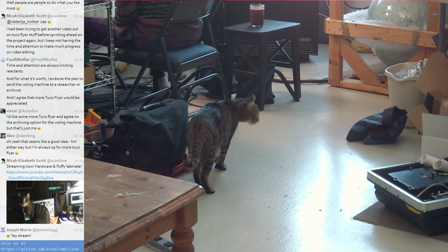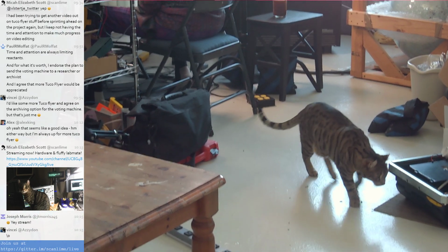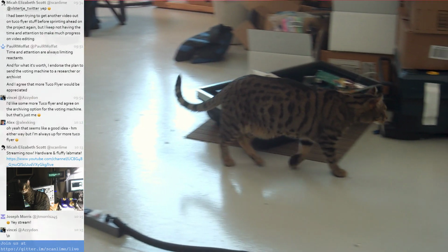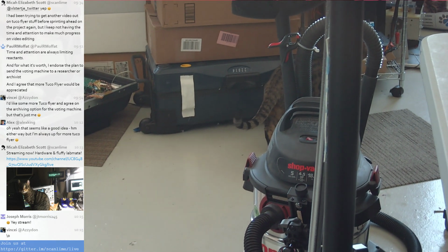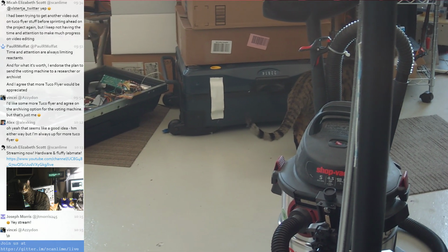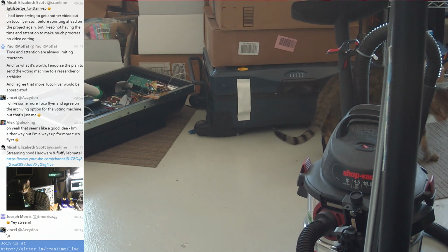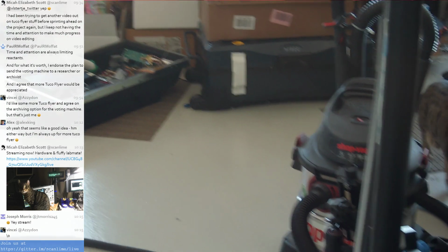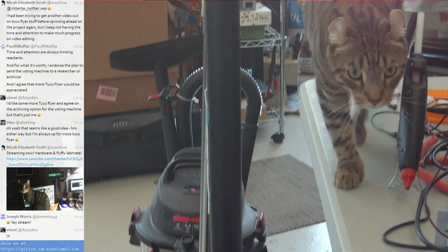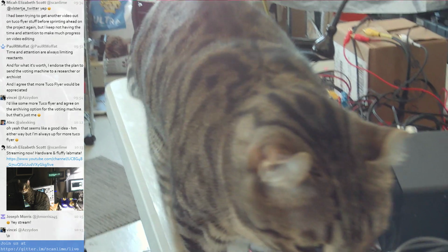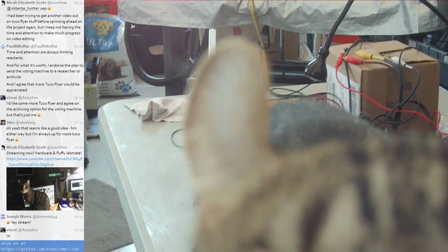There's also another pretty severe problem I've been repeatedly running into, where there's an oscillation involving this recovery feature that's designed to keep the gimbal from staying in a state that's drawing excessive power or oscillating in the motors. That particular feature is interacting badly with the computer vision sometimes.